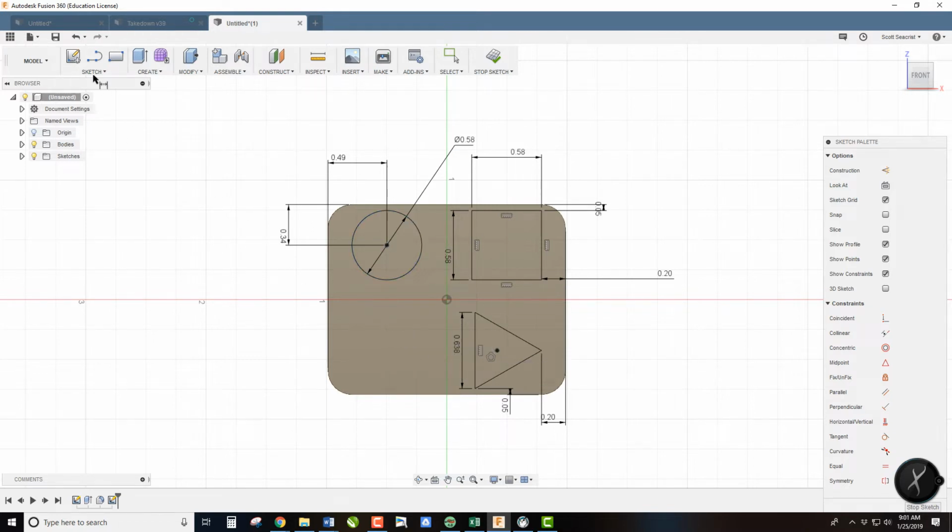It's time to do the star. For the star, we need to do 2 circles, and they both need to be construction circles. There's one. They have the same point, so I can put them in. I'm going to dimension them. The outermost circle is 0.605, and the innermost circle is 0.412.